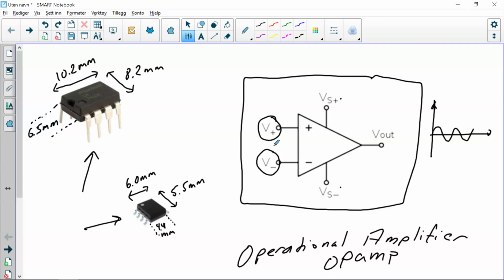Now, you always connect some components to the amplifier to build the amplifier for your specifications. So this has a very, very large gain. An extremely large, almost infinite. So it's basically like 200,000 or something. What you do is that you connect the components to it, which will reduce the amplification from infinity, or infinity more or less, to the value that you want. So if you want an amplification of 10, which means that the signal out is 10 times stronger than the signal you sent in, well, then you adjust that by adding extra components, which we will look at in the next film.